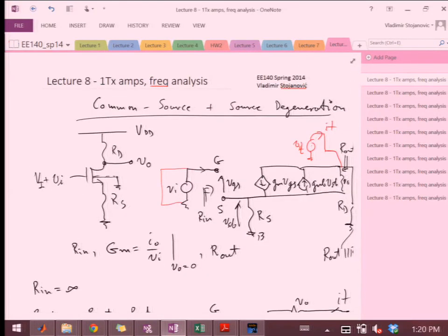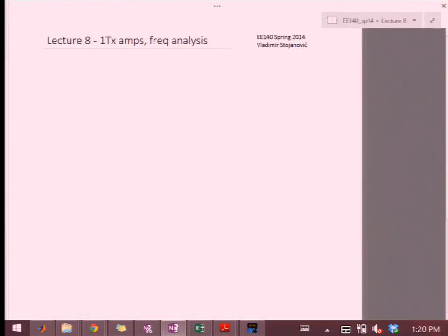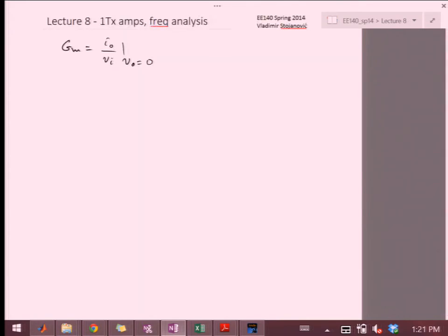which is the big Gm. Okay, so it's the amplifier Gm. Now again, let's write it out. So Gm is Iout over Vin when I ground the output, so that all the current essentially starts coming from that ground connection. So let's real quick sketch a circuit from which we'll be able to estimate that. So Vi goes into G, and then we have our source.